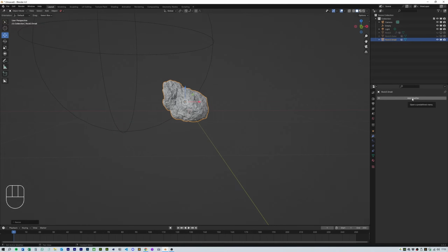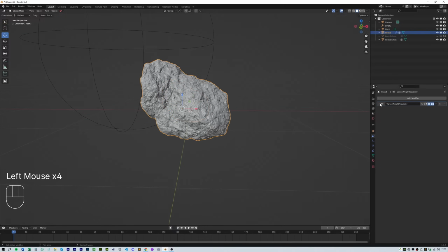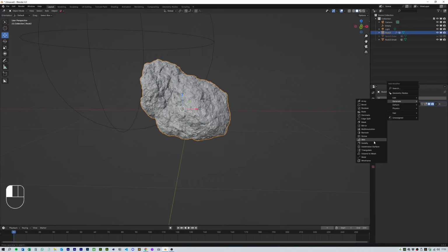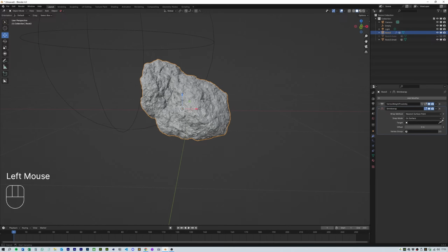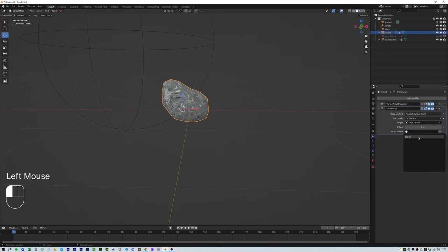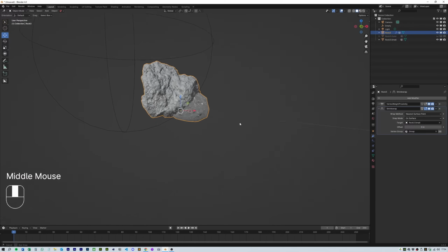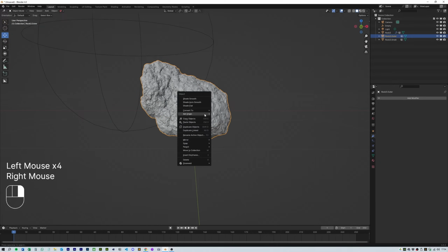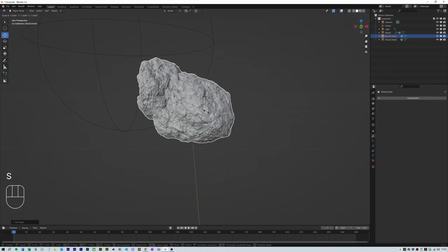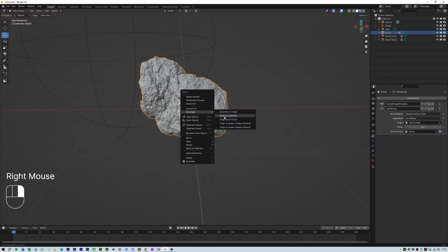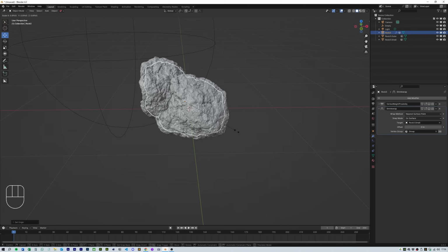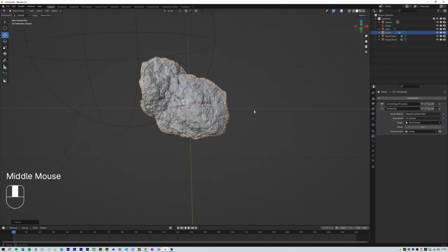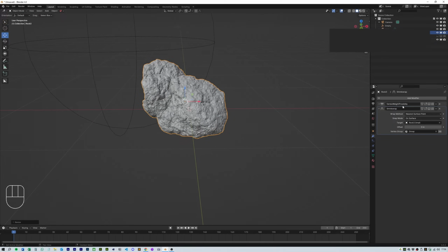Now, head over to the main rock that you've copied this from that has the weight proximity modifier on and add a shrink wrap modifier. Set the target to the new small rock and then use the vertex group that you created for the vertex weight proximity modifier and you should see something like this, which in essence is using the empty to control whether the rock is shrink wrapped to the small rock. Here I just make some slight adjustments to the big rock, always making sure that the origin is set to the geometry. Basically what you want is you want the main rock to be slightly smaller than the rock outer and that the outer covers all the way around it.